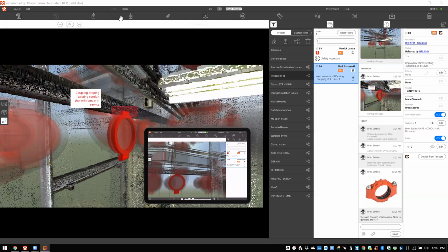The problem with it, though, is the communication and the data sharing aspect. Once we get through the parts that Navisworks is very good at, we start to create a disjointed communication method during coordination, which requires emails and IMs and phone calls and face-to-face meetings that are difficult to track. What we found is that after federating the model and providing the clash results or any information by pushing it into Revizto, you're getting the power of sharing all this information via the cloud: point clouds, models, issue information, issue properties, filters, and all of that is instantly dispersed to the greater team.